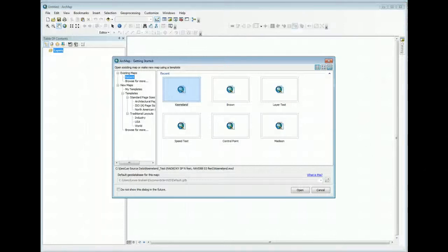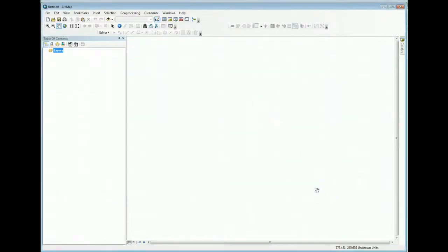The next step in the process is to start up ArcMap. I'm running Arc 10.1, but LP360 will install in anything from Arc 9.3 onward. How Arc starts up depends on which version you're using. If you're in versions prior to Arc 10.1, the minimum configuration we support is ArcView, so you can run any version of LP360 for ArcGIS and ArcView. And in 10.1, it's only the basic level that is required. Cancel out of any projects that may be trying to open.